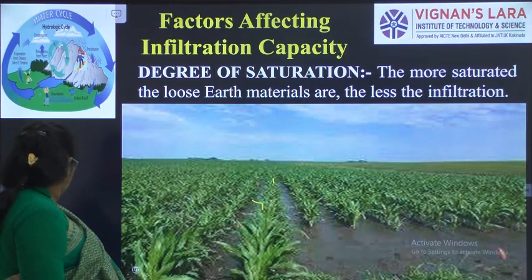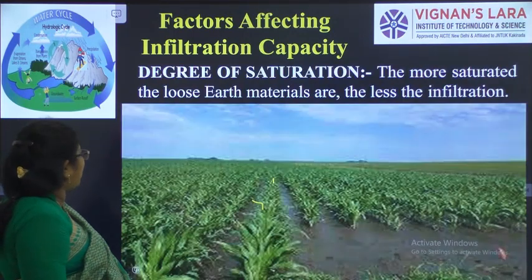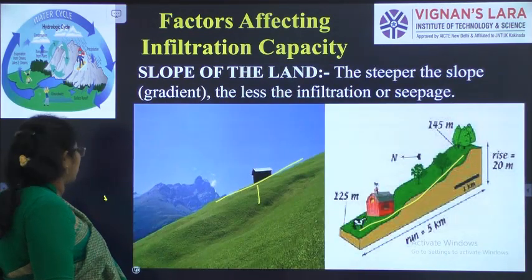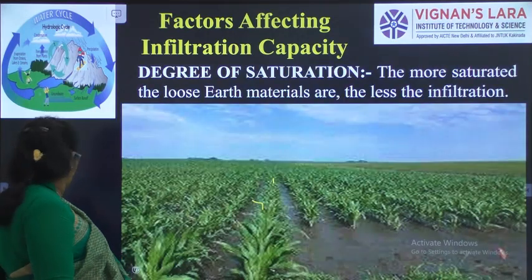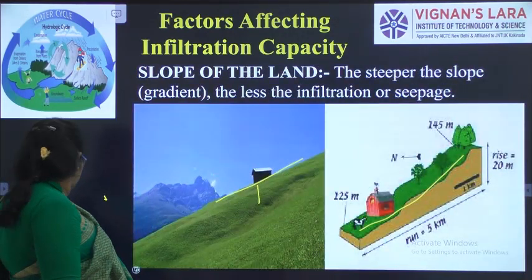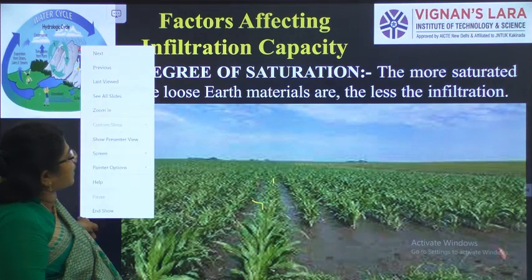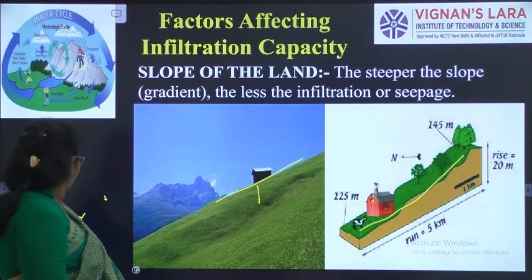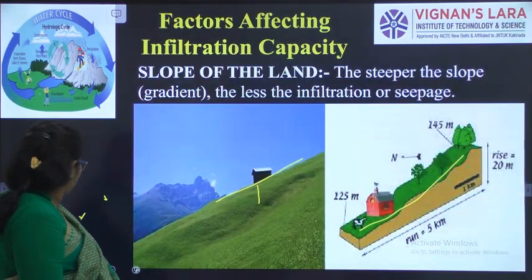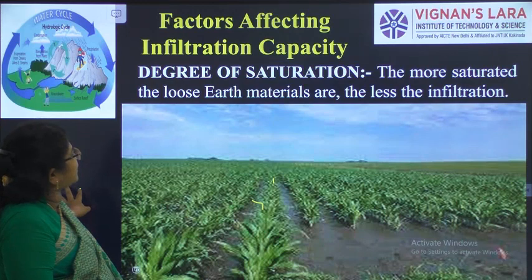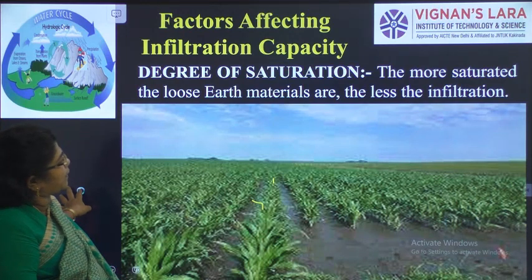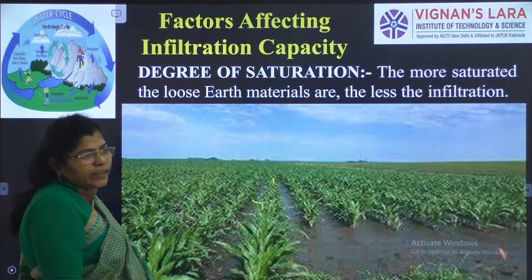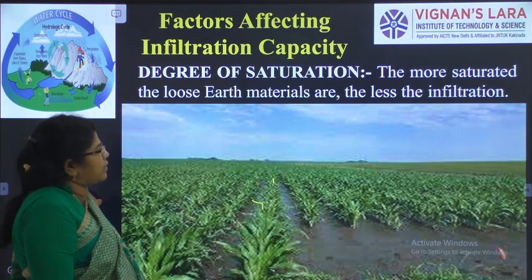So the steeper the slope, the infiltration will be less. The next one we will see is degree of saturation. The more saturated the loose earth materials are, the less the infiltration. So if there is clay content, the infiltration will be very less compared to the sand.